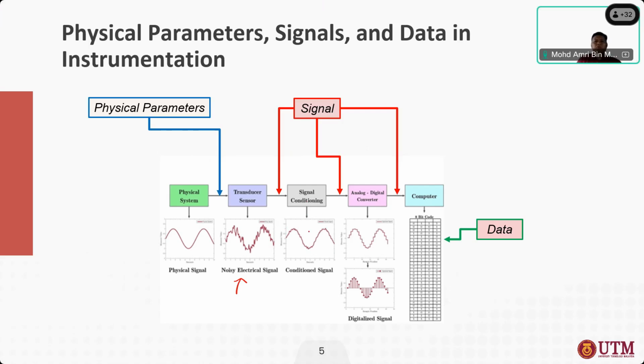To smooth out the noisy signal, we can do some process called signal conditioning, which is filtering the amount of unwanted noise. This noise basically exists at a certain frequency. Let's say our original signal is 50 hertz. It may be enveloped by noise, and the noise may be more than 50 hertz, maybe at 1 kilohertz and above. We can filter it out using a filtering circuit, for instance.